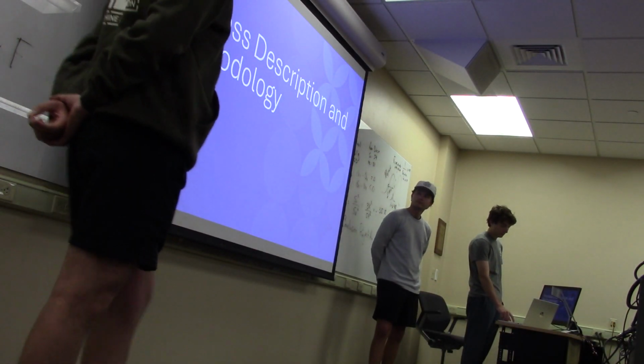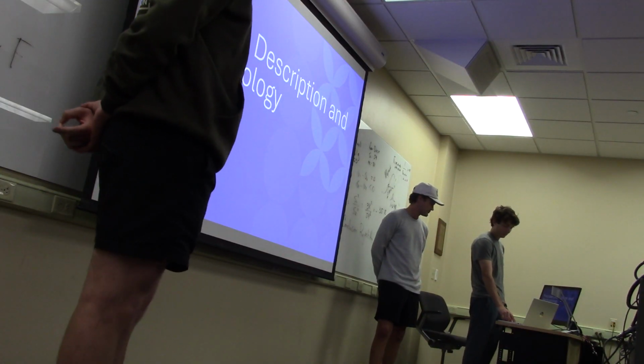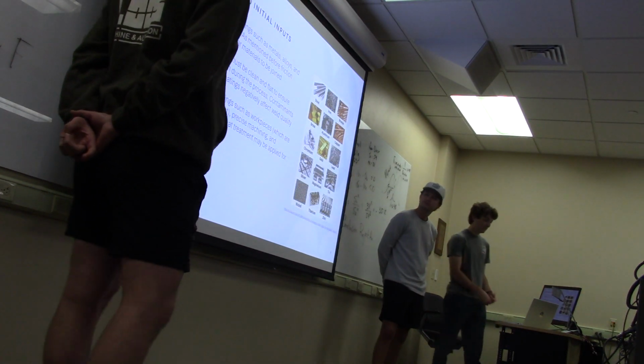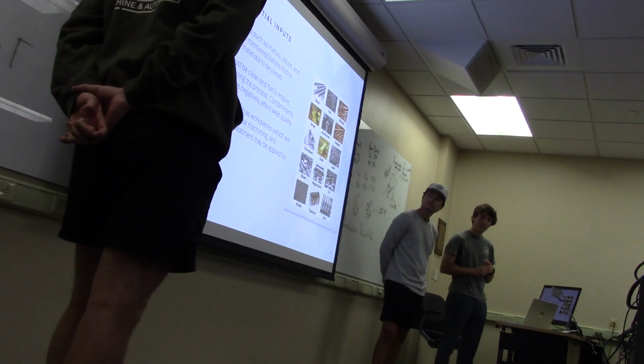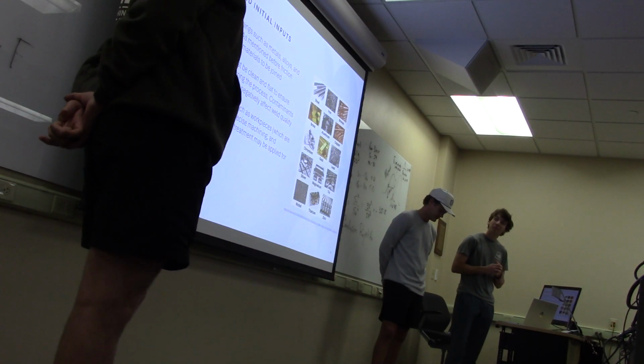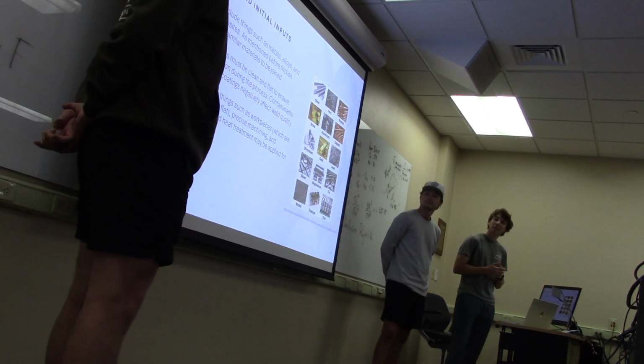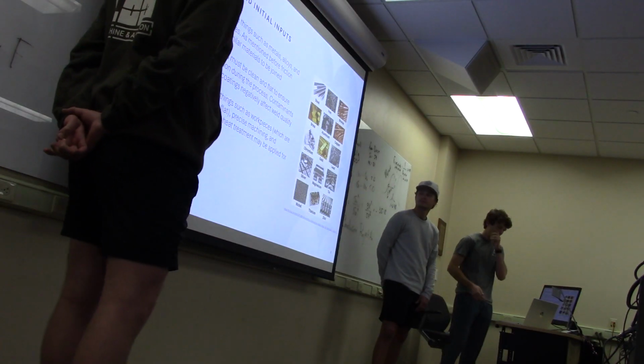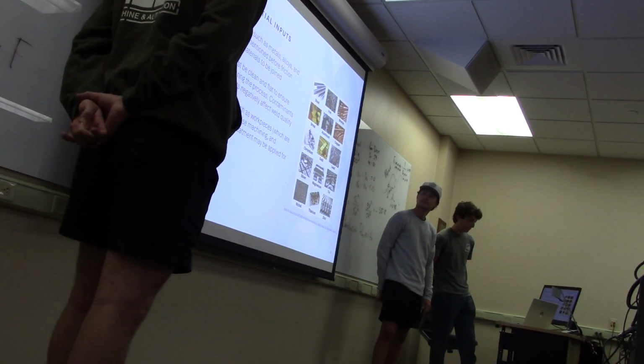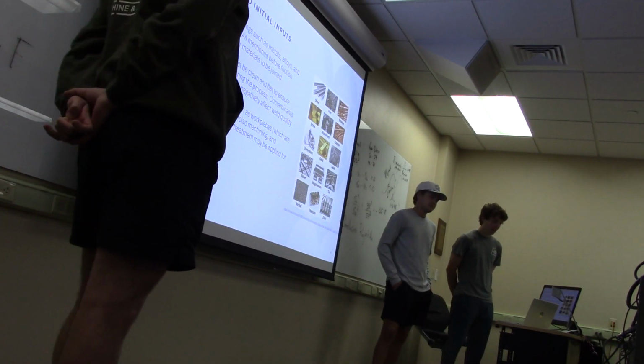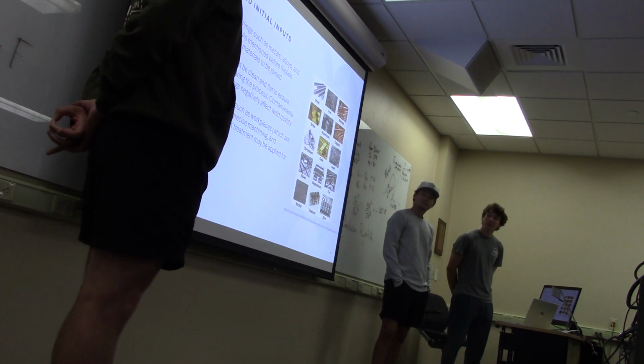Now I'm going to talk about the process description and methodology. So first off, the raw materials and our initial inputs. The raw materials include things such as metals, alloys, and some composites, as mentioned before. Friction welding allows these raw materials to be joined. The surfaces of the materials must be clean and flat to ensure proper heat generation during the process.